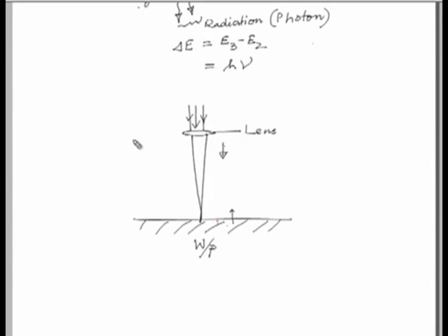Now, as it moves up, what will happen? A different portion of the laser will touch the workpiece surface something like this. Say this is the workpiece and therefore, the corresponding drilled portion will be something like this. Thus, instead of getting a straight hole something like this, we will in fact get a tapered hole something like this.